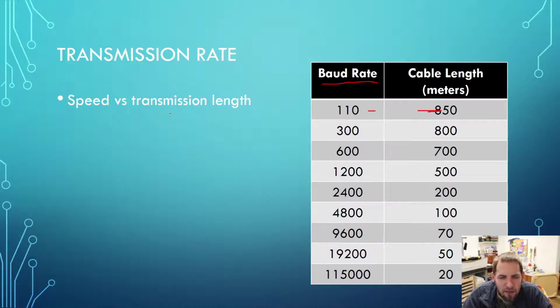But if you have thousands of feet, like 2,500 feet, 2,000 feet of wire, all of a sudden that capacitor might actually be a rather large capacitor. All right. And this is something that you always have to take into account when we are dealing with communications. So, yeah, the wires become a capacitor, and because they're a capacitor, they resist the change of voltage.